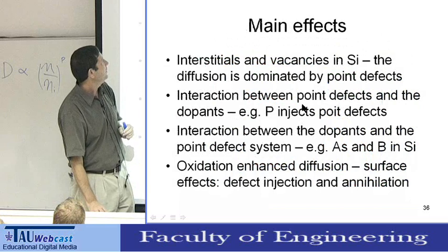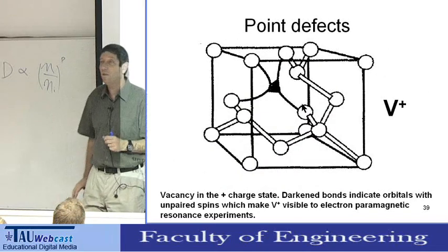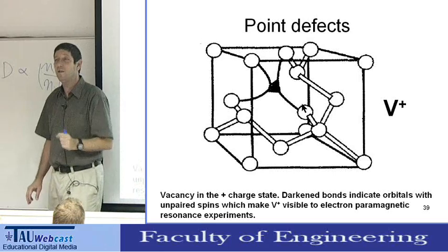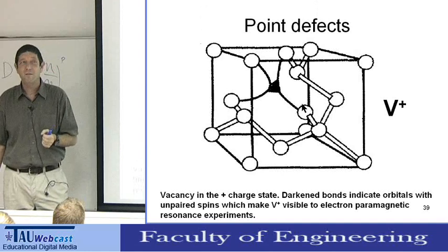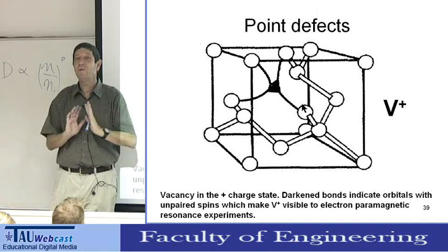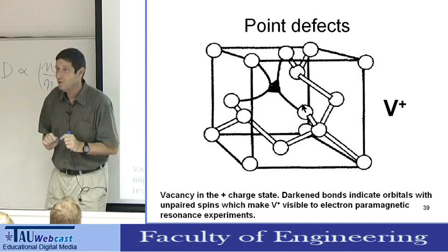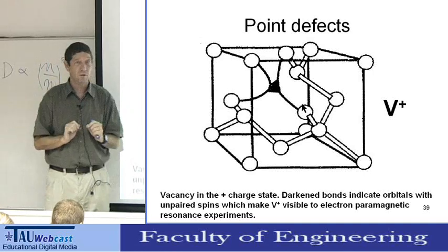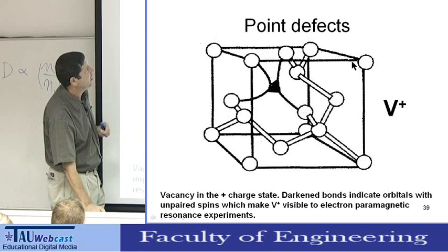And the reason, and I will skip the 2 slides, is the following. When you look at actual vacancies in silicon, the situation is more complicated, because the structure is not a 2D, it's a 3D, and the vacancies and the interstitials can be charged. For example, this is a silicon diamond structure.